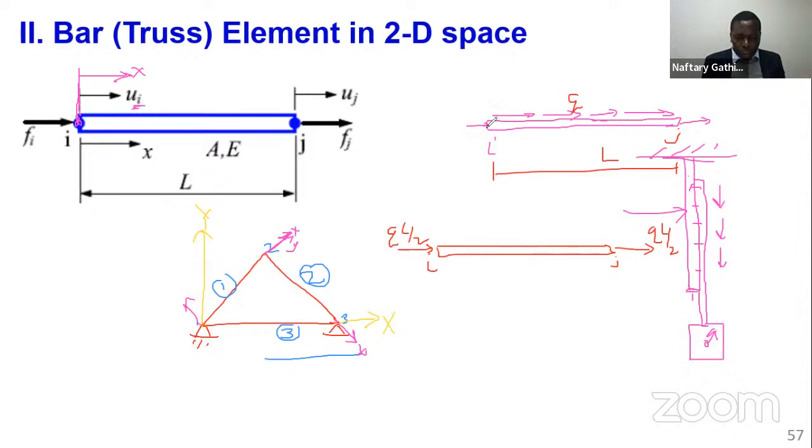If we had multiple nodes, let's say we have node 1, then another node 2 here, then another node 3 here, then in a similar case, you just need to resolve the load at the nodes. So half of this comes to this node, and half of this comes to this node. Let's say up to this point is L over 2, and then this is L over 2.